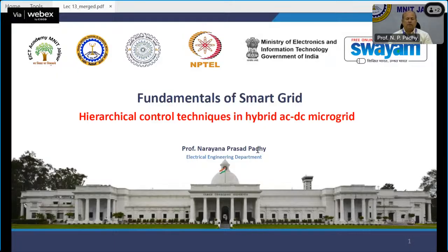The question comes when the microgrid is detached from the main grid through the ILC, which we call the islanded mode of operation, so it is completely out. And again, after some time, we can move back to the normal grid. So from a voltage regulation mode to a current regulation mode, we shift, with the grid and without the grid. So who does everything, how does it happen? You disconnect automatically, you connect automatically.